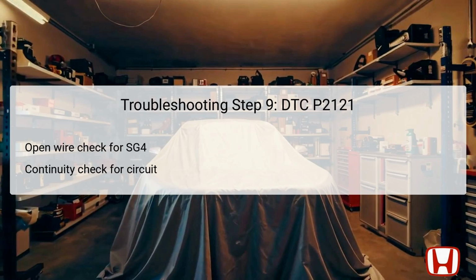If continuity is confirmed, it underscores the soundness of the SG4 connection, which allows further analysis or PCM substitution as options. However, if no continuity is apparent, the technician must promptly repair any breaks along that line to restore proper function and clear the DTC P2121.